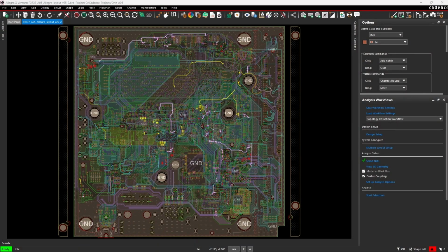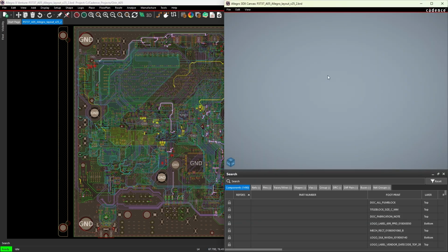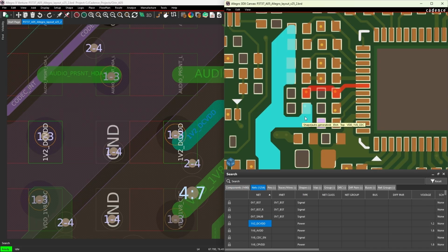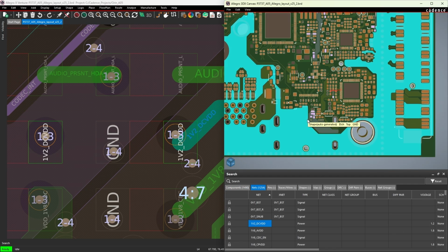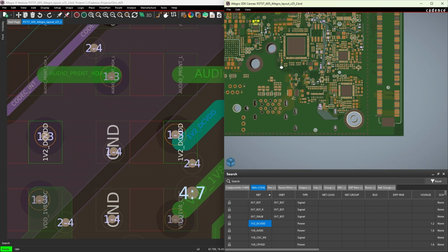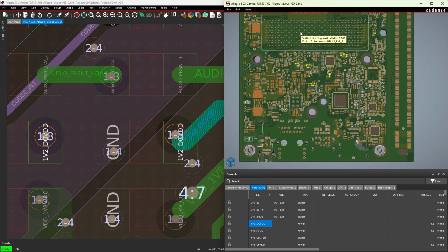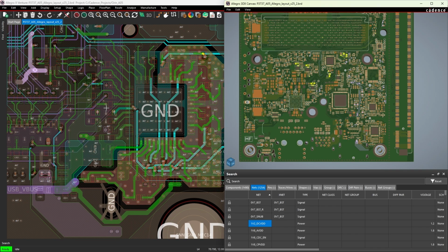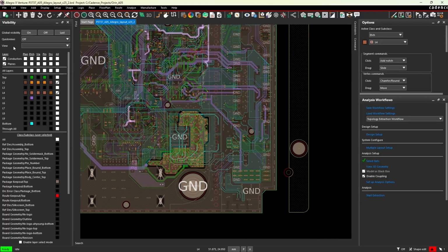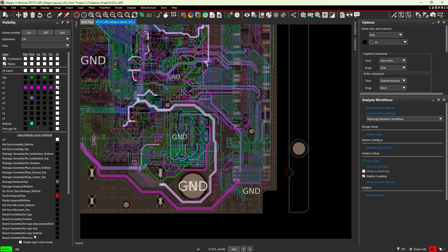So let me show you what I'm going to do here. Here I have a board from Nvidia. This is an astounding piece of engineering and it's beautiful. It's a 10-layer printed circuit board that has a ton of traces, vias, micro vias, and an HDI, or high density interconnect, stack up, and a lot of pins and connectors. Let me show you the different layers; especially on layer 3, our PCIe.